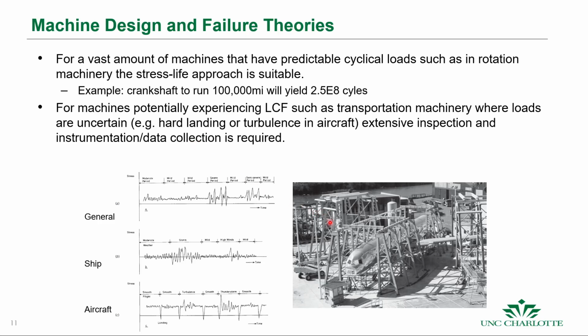This is an image here of, I think it's Boeing doing a structural test on their airframe. And this is sort of what you might see as a time trace if you're collecting that data. As you can see, there are portions where the vehicle's in service and then experiences higher than normal loads, and then normal service, and then maybe a storm or whatever like that. These loads have to be accounted for in those particular designs.